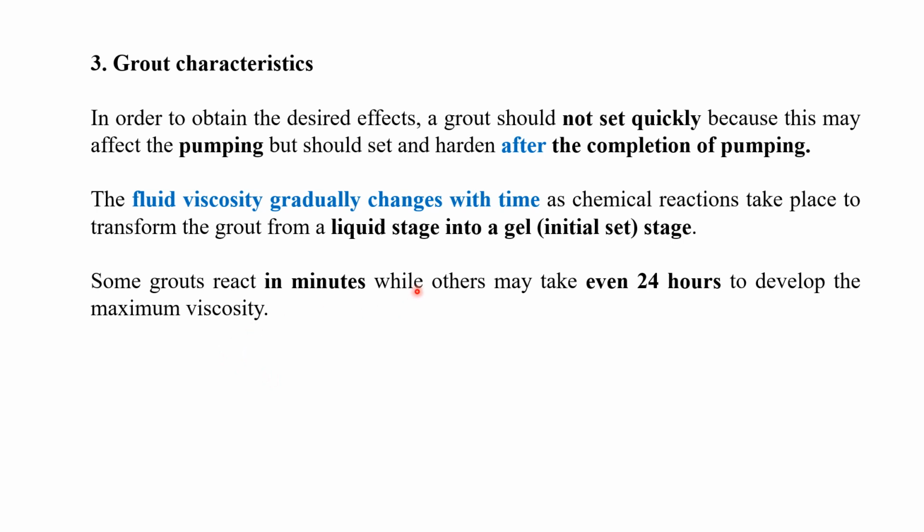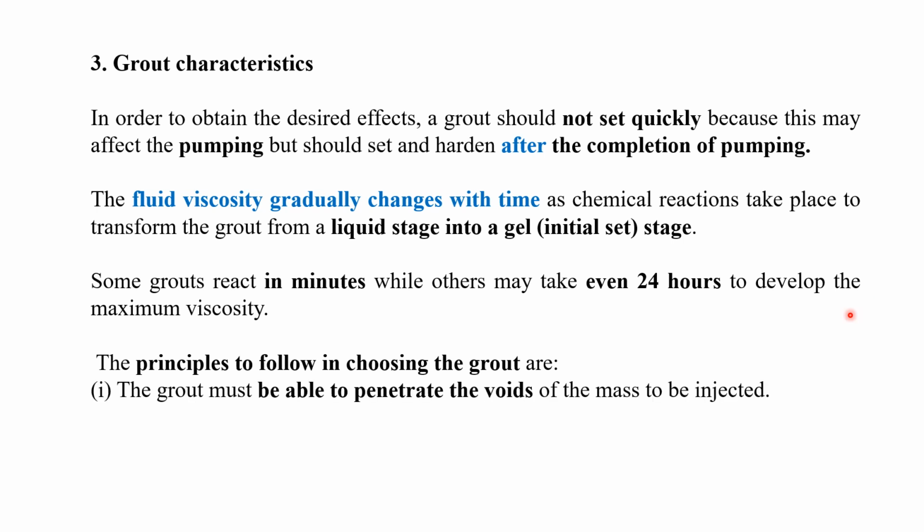Some grouts react in minutes, while some may take 24 hours, depending upon the chemical reactions. The principles to follow in choosing the grout: whenever we are going to choose the grout, what factors should we consider? What should be the properties of the grout? The first property is that the grout must be able to penetrate the voids of the mass to be injected.